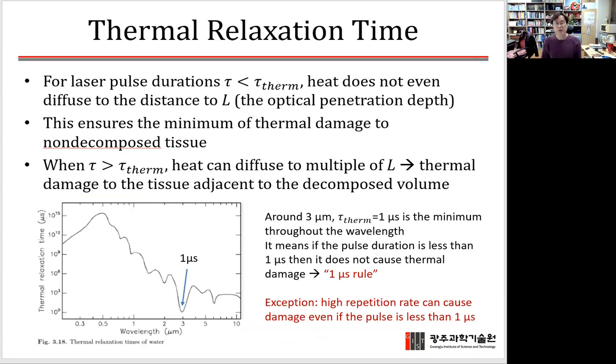For the laser pulse duration tau, if this duration tau is smaller than the thermal relaxation time, then basically heat does not even diffuse to the distance of 1/α.